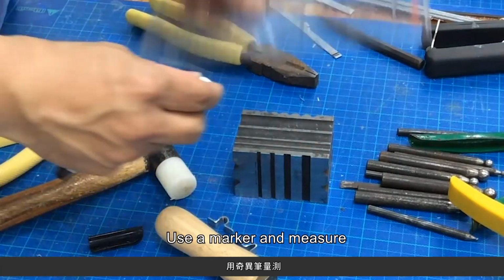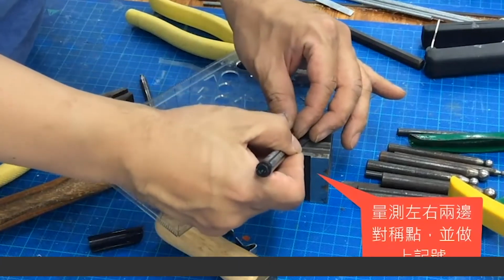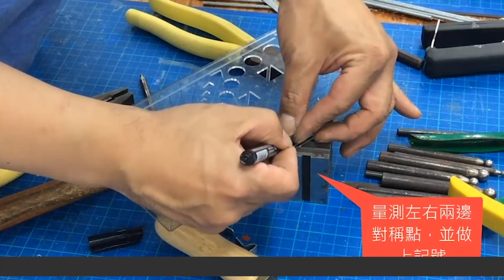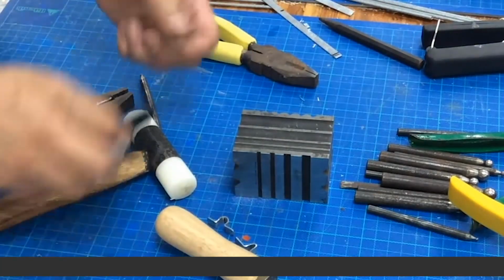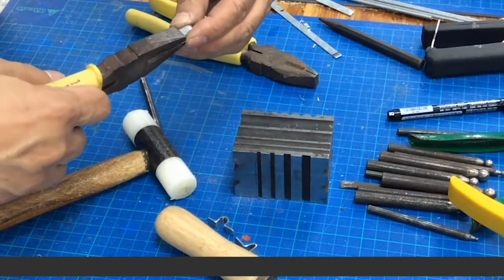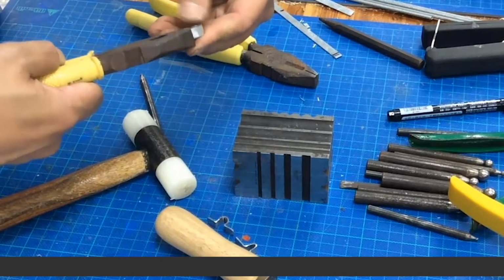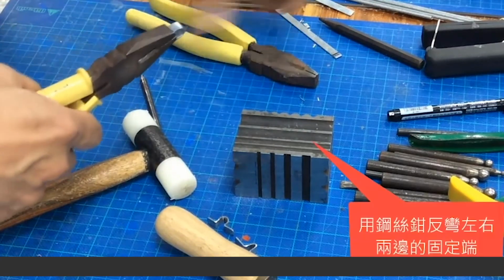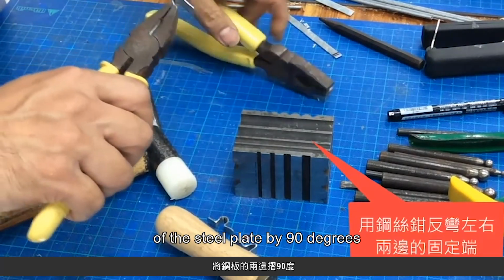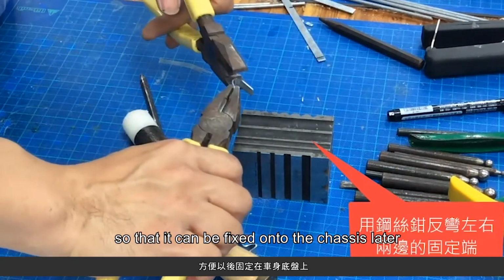Use a marker and measure the left and right sides and mark the symmetric point of hemming. Use wire cutters to bend both sides of the steel plate by 90 degrees so that it can be fixed onto the chassis later.